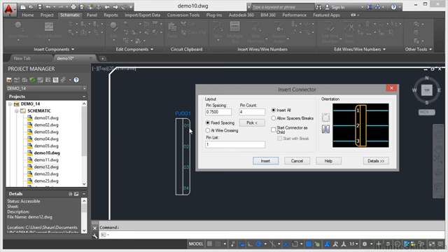There's a reason for that. I like to have zeros in front of my single digits, so 01, 02. I'll change that there to 01, to give it a numbering philosophy when I bring the pin into the AutoCAD electrical drawing. I'm going to change the pin count to 6. I'm going to leave it at the fixed spacing of 0.75.